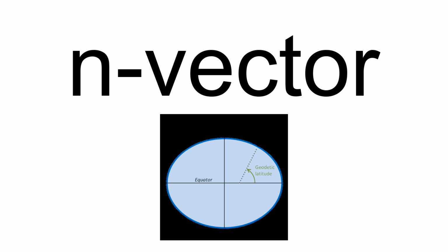The n-vector representation, also called geodetic normal or ellipsoid normal vector, is a three-parameter non-singular representation well-suited for replacing latitude and longitude as horizontal position representation in mathematical calculations and computer algorithms. Geometrically, the n-vector for a given position on an ellipsoid is the outward-pointing unit vector that is normal in that position to the ellipsoid. For representing horizontal positions on Earth, the ellipsoid is a reference ellipsoid and the vector is decomposed in an Earth-centered Earth-fixed coordinate system. It behaves smoothly at all Earth positions, and it holds the mathematical one-to-one property.